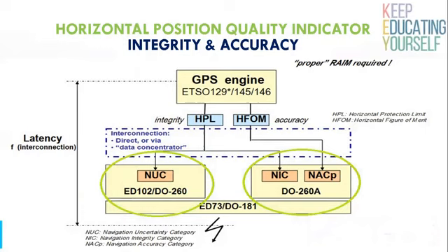In order to allow the use of airborne position information in surveillance and radar-like separation service, the parameter Horizontal Position Quality Indicator would be provided together with the position by the ADS-B airborne system. The parameter which expresses the quality and credibility is based on the integrity and accuracy of the horizontal position information which is transmitted by ADS-B.